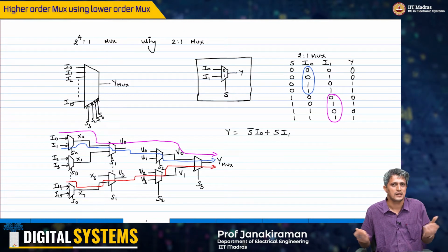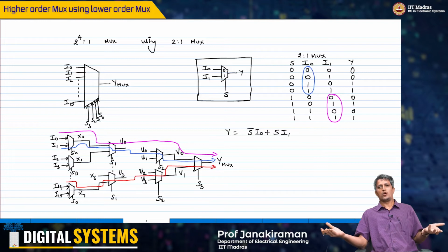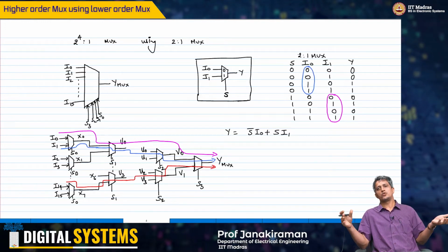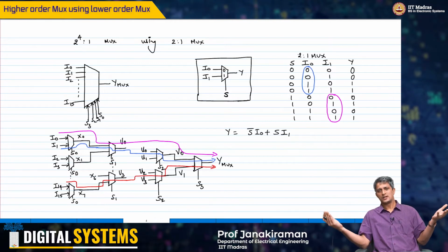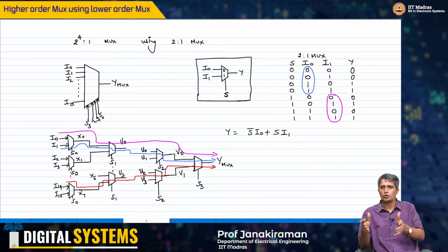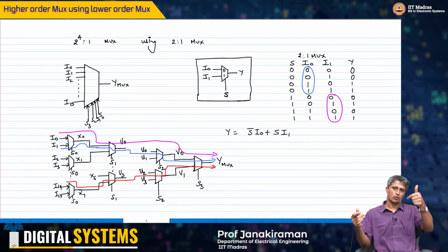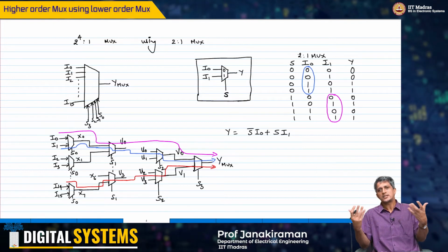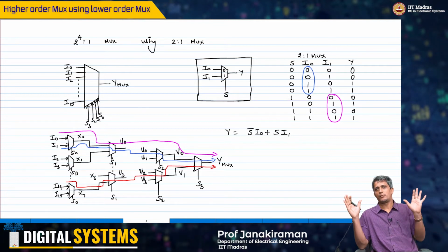So effectively, just like you saw with the decoder, in order to build a hierarchical decoder, we had to start with a decoder on the output stage, then divide by 2, that we needed a decoder for that many outputs in the previous stage, again divide by 2, keep dividing by 2 until you reach the point where your smallest decoder or multiplexer can accommodate those number of inputs.